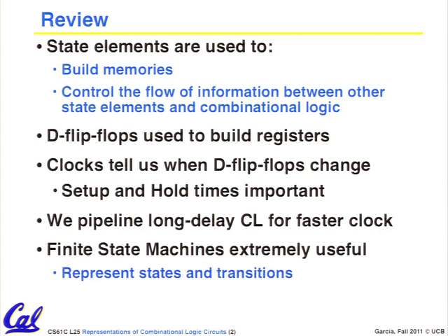And at the end, we talked about finite state machines as being a great and really efficient way of encoding a kind of brain. For example, I've taken a coin, now I've taken 5 cents, but I haven't taken a full dollar yet, so I don't release the soda. That's the idea of a finite state machine. We saw the particular example of counting 3 ones in a row, and not 4. If it gets to 4, it resets. It has to have another 3. So it sees 3 and resets.